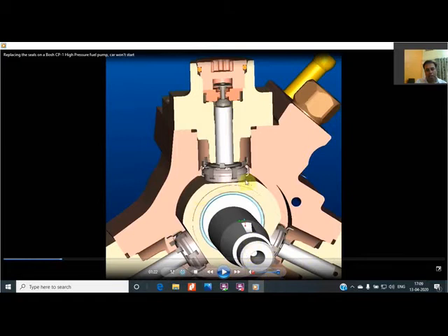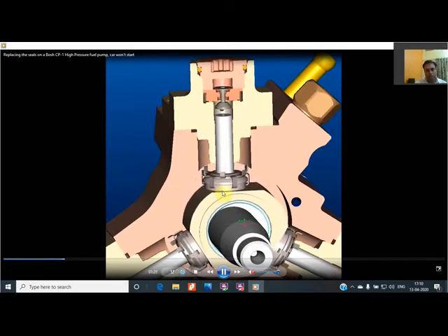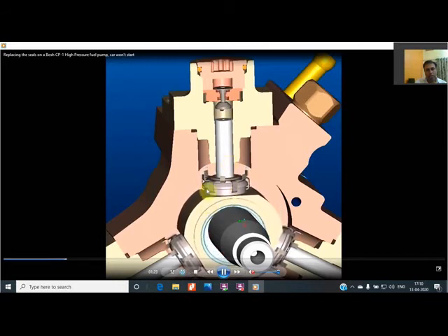And this is the cam driven shaft. This complete rotor has such a mechanism that in a single rotation, if your camshaft is rotating at half the RPM of the engine, as all know that the camshaft runs at half the RPM of the engine, it gives upward motion to this plunger thrice. Means three lobes are there, first, second, and third. If you see the video also, when the first lobe comes below it, it will move it up, and then the second, then the third.